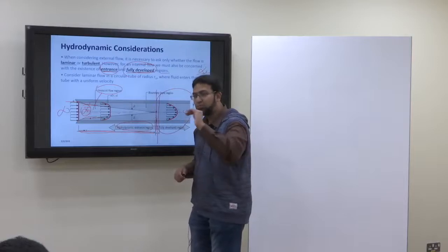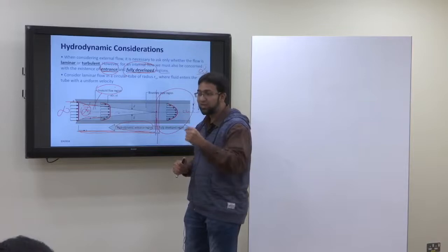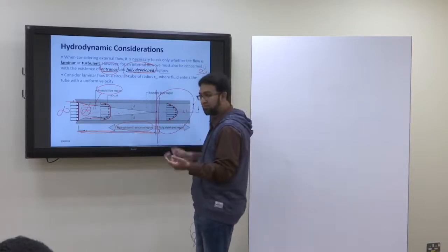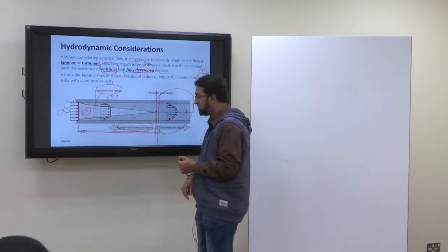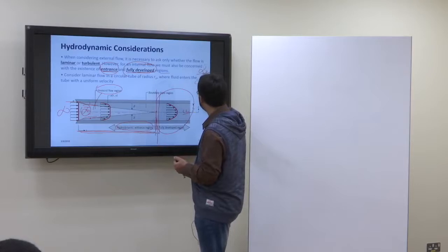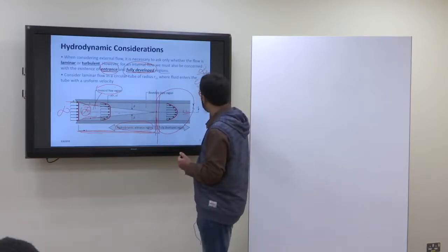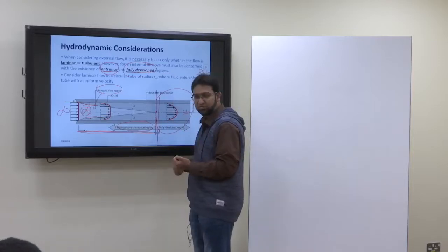So they stop at a certain point which is less than free stream. However, that is the maximum velocity in the pipe. So that's the center line velocity. You have the center line velocity, the free stream velocity, and the velocity at the surface, which is 0, obviously.